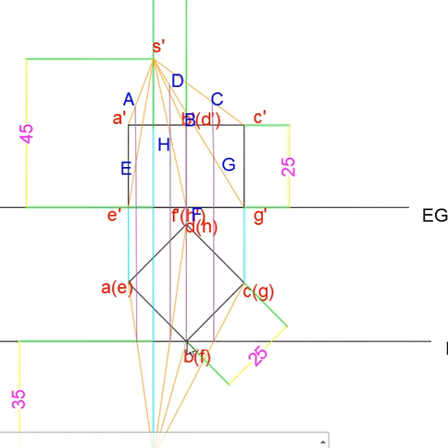Since one point is resting on a picture plane, BF is not a point, it is actually a line. It will appear like a point in top view, but that is a vertical edge. So BF line is completely visible. We can draw the vertical edge like this.